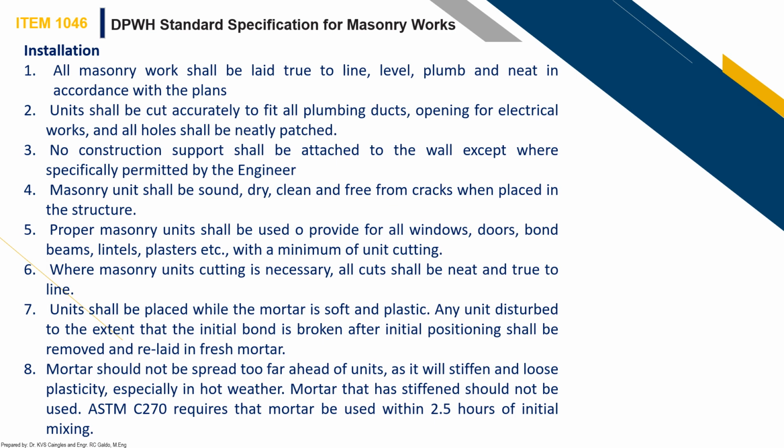And also, aside from the construction requirements, is the provision of DPWH as to the masonry works or item 1046 with respect to the installation of your concrete masonry units or your CHB. So, okay, this is a step-by-step procedure on how to properly install your CHB or concrete masonry units diha sa imuhang masonry works.